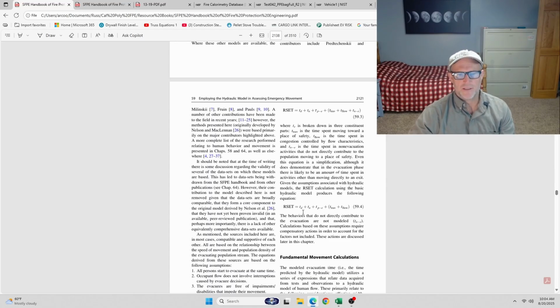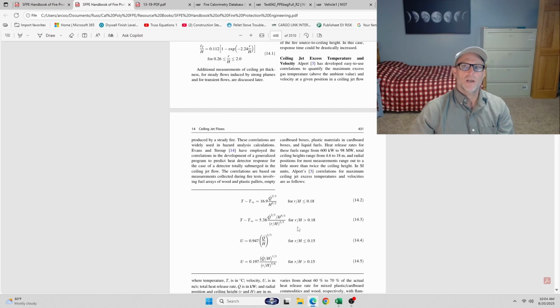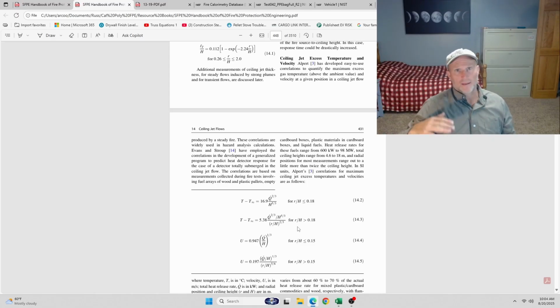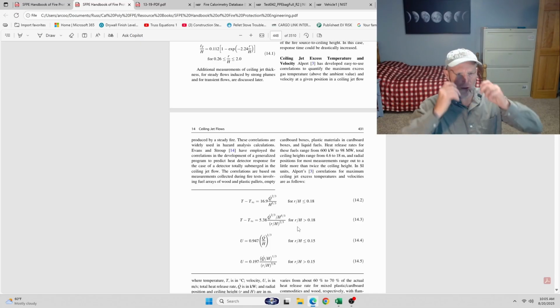And a piece of that is detection, but another piece that needs to be considered sometimes is the performance of the environment. So typically smoke layer level is capped at 6 feet. So if you're below that level, you've basically made that egress access path problematic. You're going to be slowed down for that.